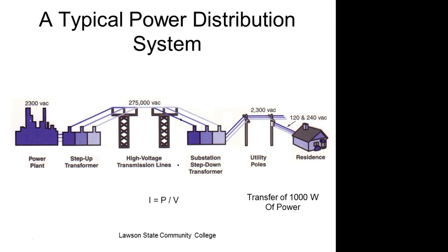But where do they hide them at? They hide them. They have to be mounted down on the floor behind the appliance. So to get to your 240 plug, you literally got to pull these things out to get to them. And then of course some devices are hardwired, like water heaters and stuff like that. If you want to turn those things off, you gotta go in and trip it off with your breaker, right?